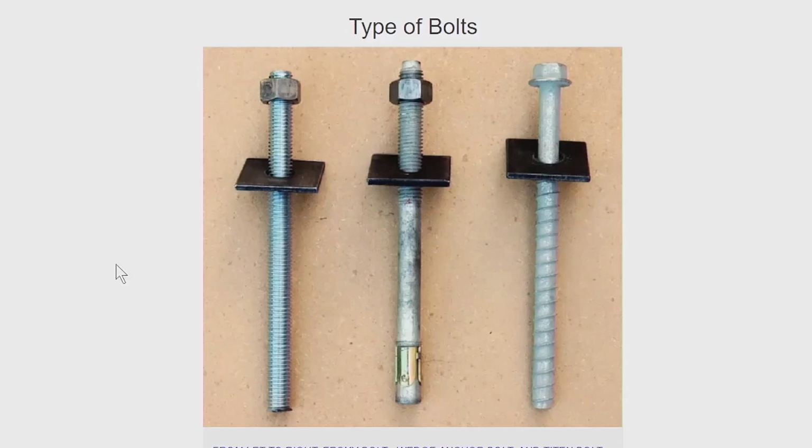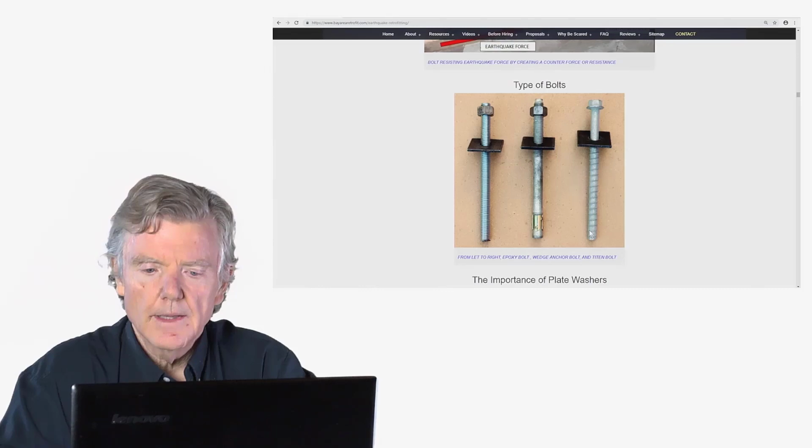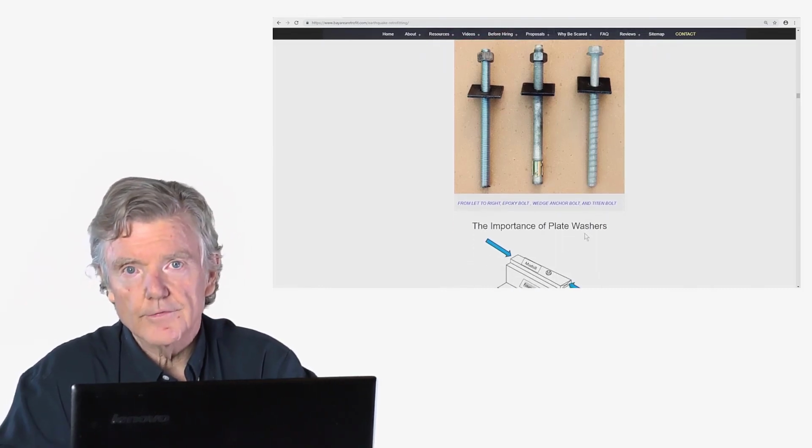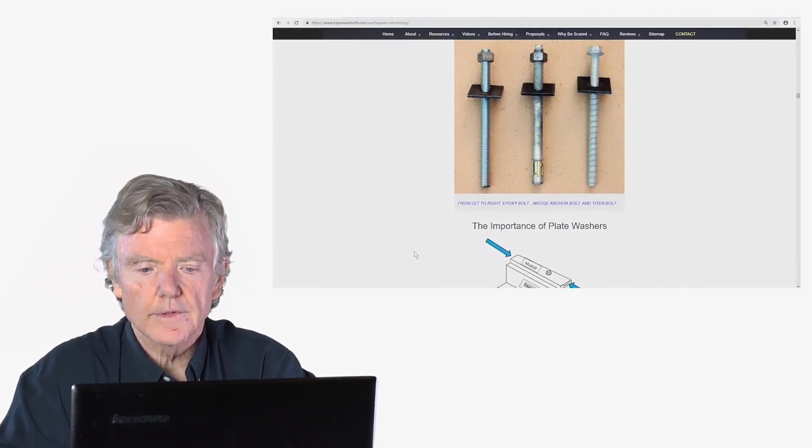So here's a type of bolt. Usually these work, that's called a wedge anchor. Sometimes we have to glue them into the concrete if it's not very good. And in some cases, if it's medium hard, these work pretty well as well. So those are the three types that you can find. Again, foundation anchors are also another type, and we saw those earlier.